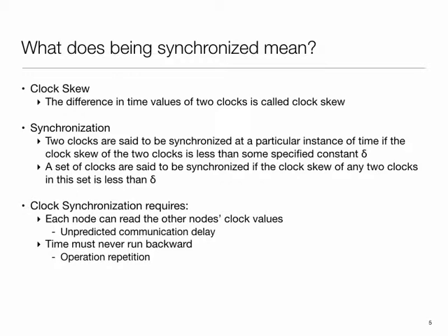You can slow down the clock. Yeah, you slow down the clock. So you aim to let the other party catch up with me, right? So you either actually change the frequency of your oscillator if it lets you do that, or alternatively you apply a corrective factor.